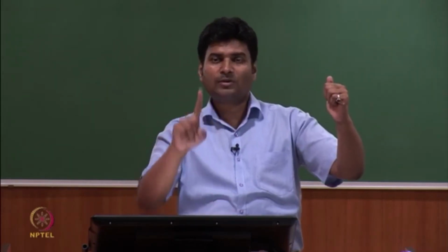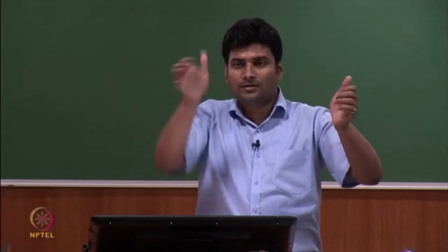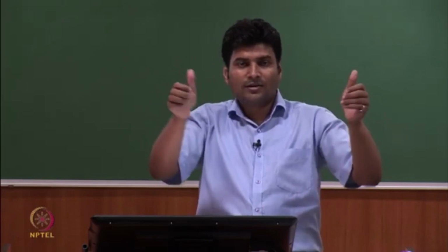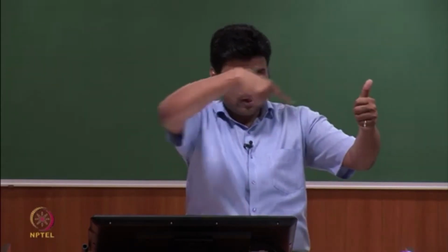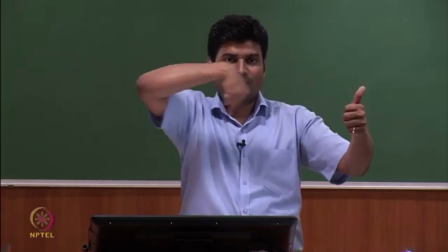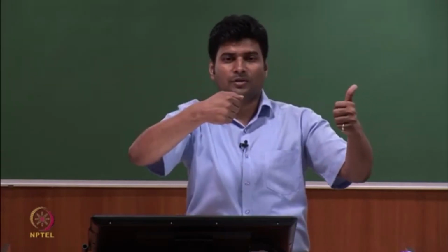Now, think of applying moment about y axis. So, when we have moment about y axis, so what is going to happen? When you apply moment about y axis like this, then your beam bends in this way, it curves towards me.